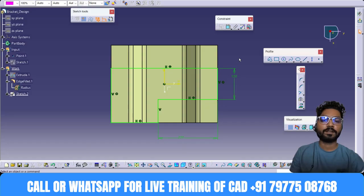For the fillets, you can select the corners by pressing Control and select all corners. Once you select all corners, the middle corner is pending, that also you can select: this middle corner, then this one, then this one. Just drag a rectangle so you can select it properly.